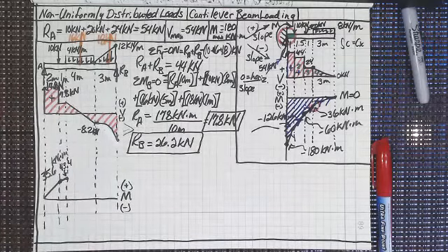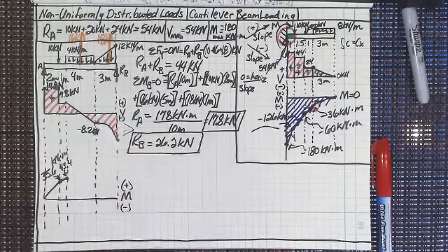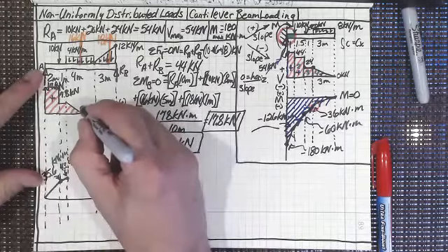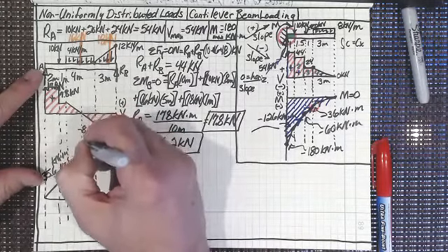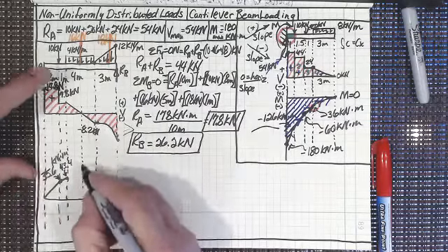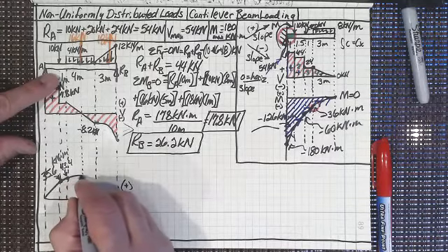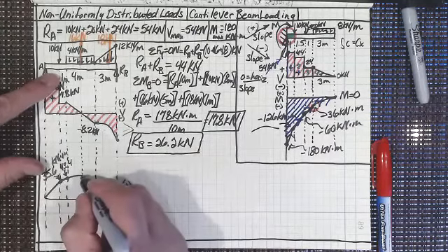35.6 is right there, and 43.4 kilonewton meters is right there. Now we go down to 0, don't we? In fact, we know where we're going to get to 0. We're going to get to 0 right at this point. So it's going to continue that direction, and then it's going to flatten over towards 0 right at that point.